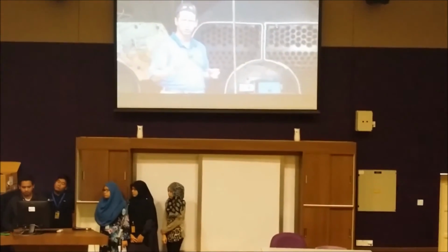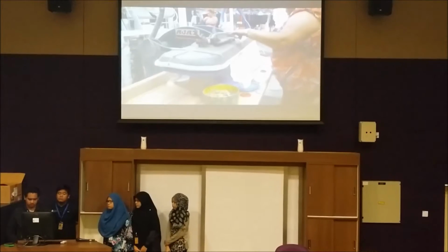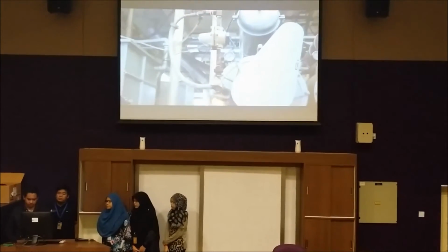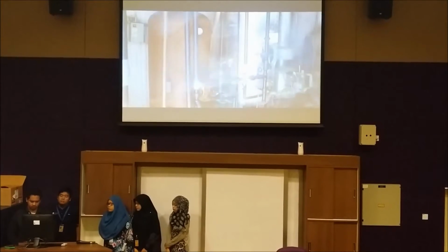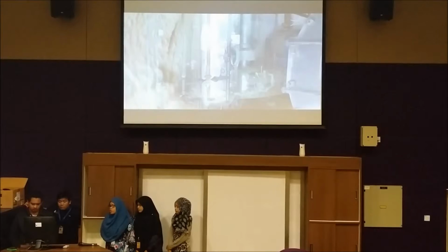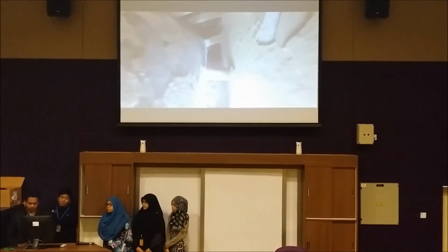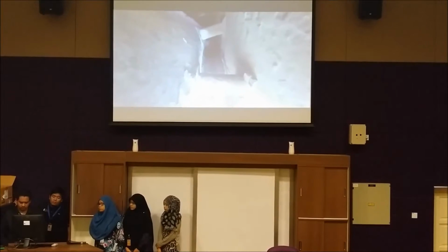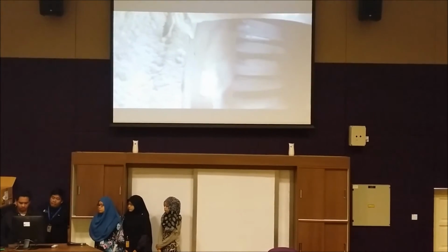Let's talk about scale a little bit. Scale happens because of impurities that are carried in the feed water. As a steam plant operates, there's going to be steam losses in the system. To make up for those steam losses, there's going to be makeup water that's brought into the steam system. That makeup water carries impurities with it. There's a tendency, if the water chemistry is not kept right in the boiler, for those impurities to plate out on the internal surfaces of the boiler in the form of scale.